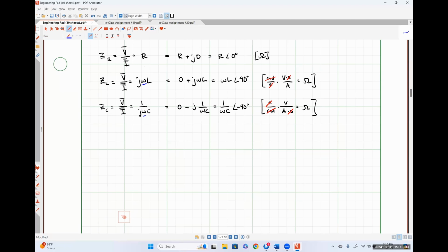A short circuit, where a short circuit is characterized by having no resistance. So our impedance equation exactly agrees with what we've observed previously in the class, right? At very, very low frequencies, an inductor behaves like a section of wire or a short circuit, which means that its resistance or impedance value is 0.